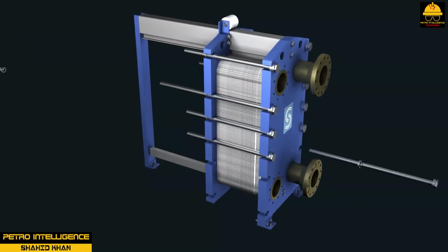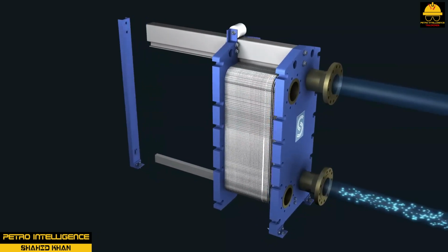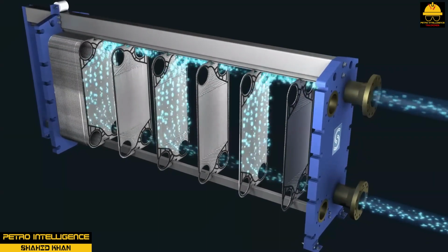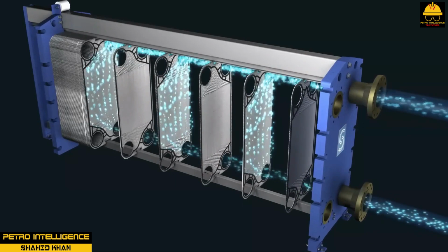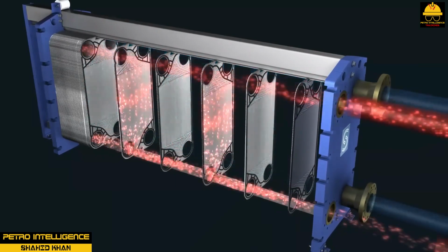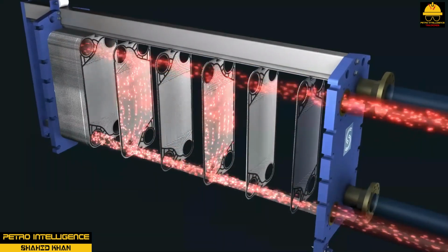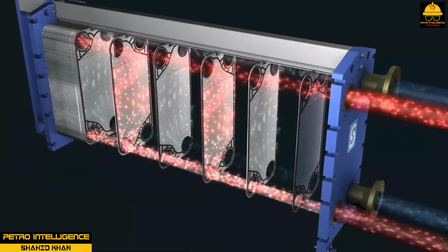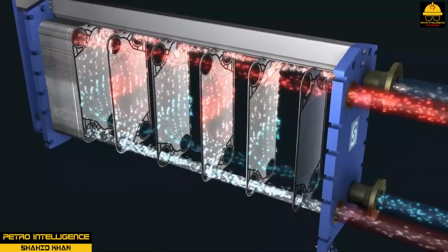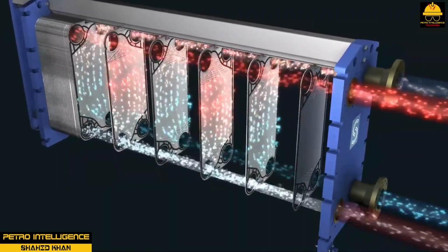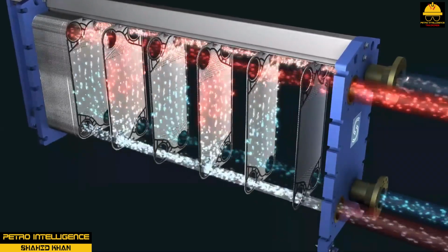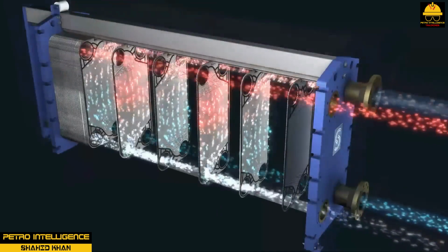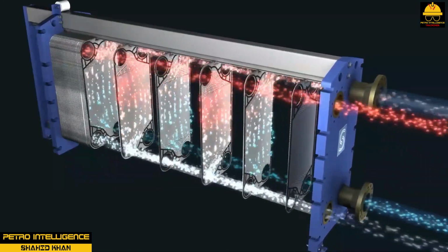The thin plates separate the hot and cold liquids, preventing leakage. Fluid flow passes across the plates one time before entering the collection header. The plates are designed with an alternating series of chambers. Heat energy is transferred through the walls of the plates by conduction and into the liquid by convection. The hot and cold inlet lines run the entire length of the plate heater and function like a distribution header. The hot and cold collection headers run parallel and on the opposite side of the plates from each other.